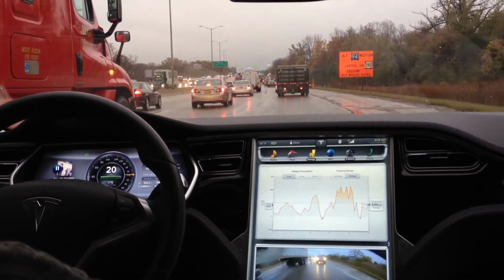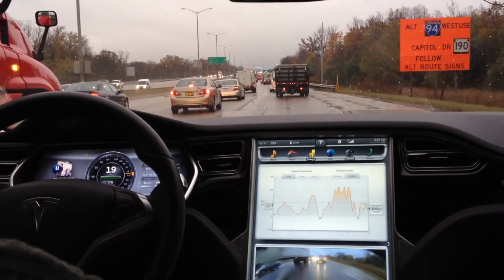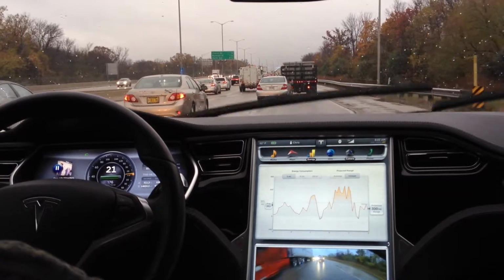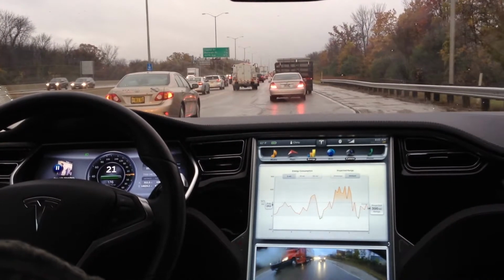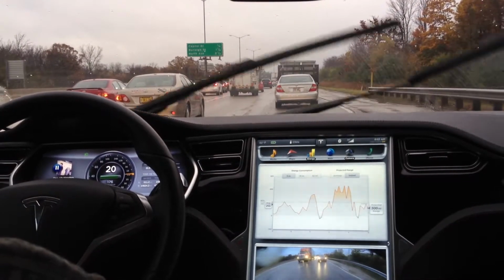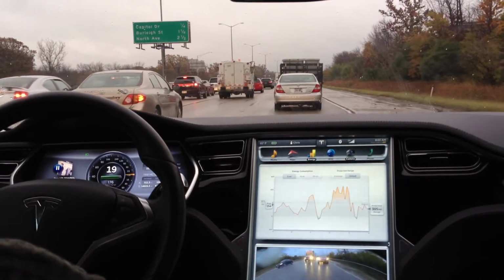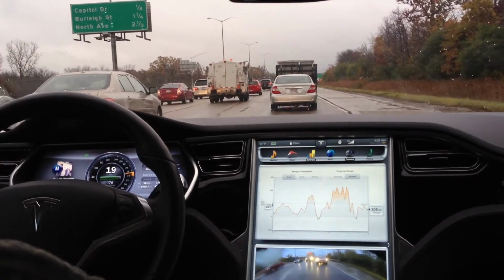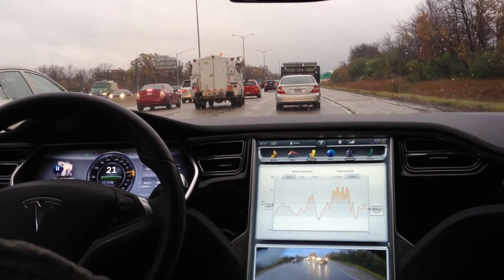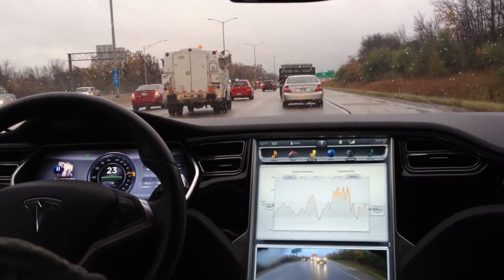So you've got that 100-watt light bulb. If that light bulb was on for 10 hours, you have just consumed 1 kilowatt hour, which is what your power company is billing you by. So if you run that 100-watt light bulb for 10 hours, it would cost you, national average is about 13 cents a kilowatt hour. My time of use for nighttime usage would be 5 cents a kilowatt hour. See where I'm going with this?